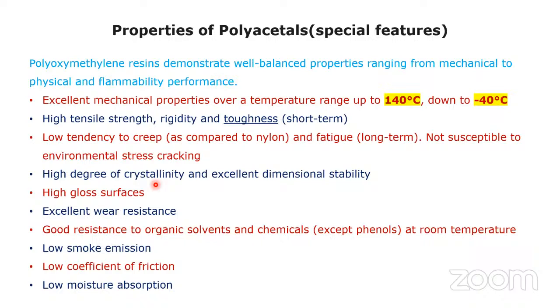Okay, but if you compare, suppose some polypropylene material is there, correct? Have you seen that it will shrink more than polypropylene? Yes, sir. Polypropylene, even it will shrink after 1 or 2 days also. Slowly there will be a change in dimension after even 1 week also. But after 1 week, it is stabilizing. Dimensional change will not happen. Polypropylene, you are telling. Yes, polypropylene.